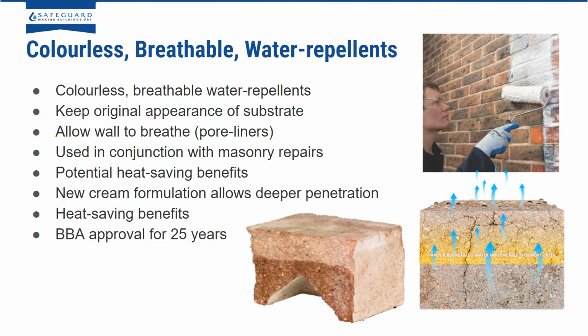But so 90% of the water vapor will carry on passing through the brickwork. The other benefit of using them is that they can also have heat-saving properties. So by keeping the wall dry, you're preventing that heat transfer, and so that also reduces people's heat loss through the wall. So these have been found to be very effective and also have a long lifetime.